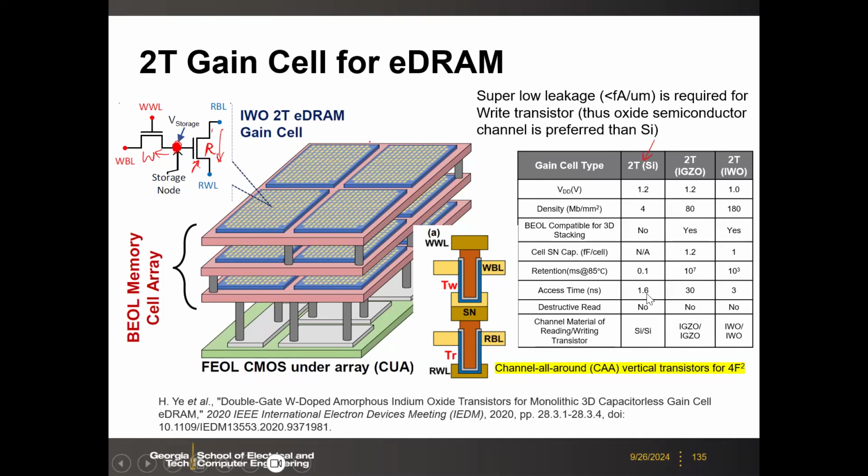And the big challenge here is that because you have the logic transistor, the off current actually is high, right? Compared to the DRAM access transistor. Therefore, the retention is also not good, in the hundreds of microsecond range. So they suffered the same issue as the 1T1C silicon eDRAM.